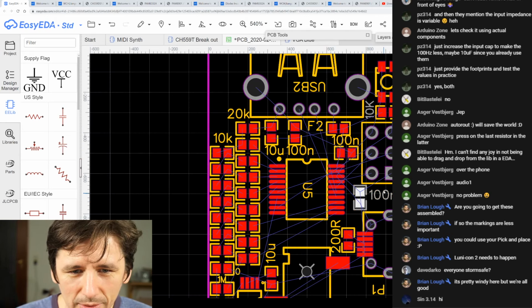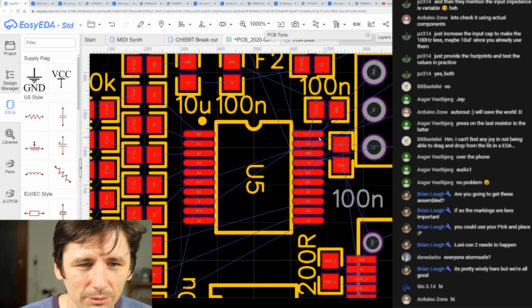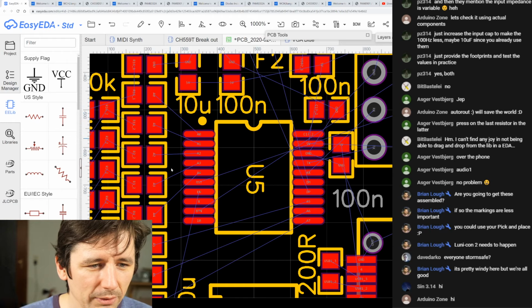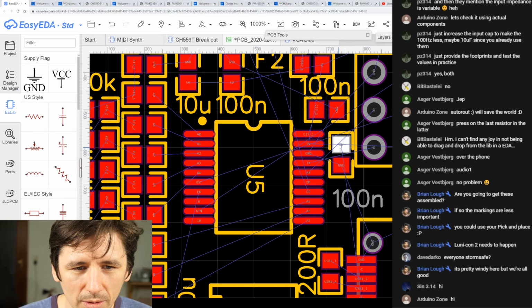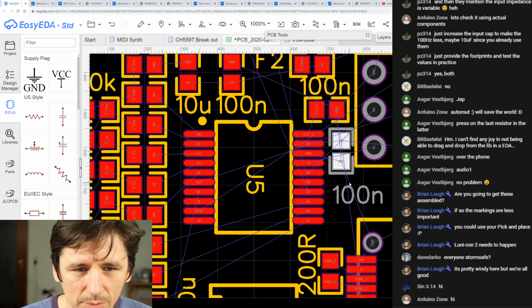Yeah, there are all like 10. Maybe I could even move it more up, but I don't want this resistor or this capacitor to be too close. Oh, but that fits. Is it too close? I want some space for wiring here, since this will be tied anyways. So this might be a little bit too close. TX, RX, there will be some wiring here. Maybe like that.